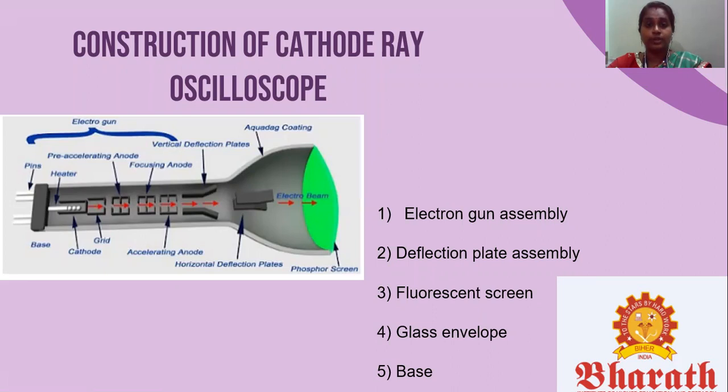When an electron beam strikes phosphor crystals, it raises their energy level. This is called cathodoluminescence. Light is emitted during the phosphor excitation, and this is called fluorescence. When the electron beam is switched off, the phosphor crystals return to their initial state and release a quantum of light energy. This is called phosphorescence or persistence.